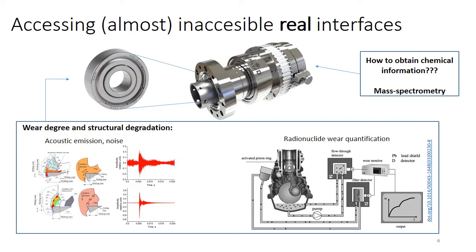So what can we do to characterize friction and wear on real interfaces which are really buried and very difficult to access? Unfortunately, only a very limited number of techniques are available now, and I can mention here the acoustic emission and noise, which allow to obtain information about fracture processes and deterioration, crack propagation at the interface by measuring the acoustic emission and noise.